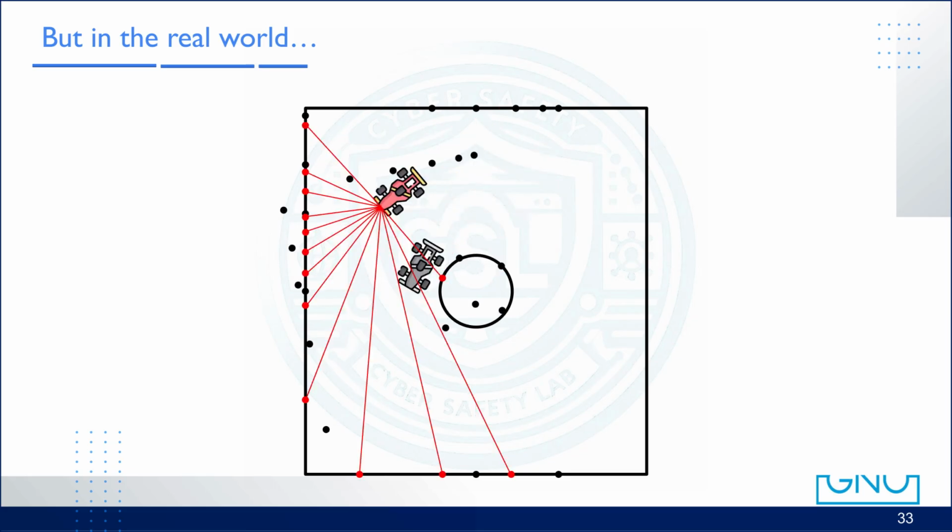In the end, scans accumulated on top of incorrect odometry produce a map that no longer resembles the real environment. Points drift away from walls, straight structures become warped, and obstacles lose consistency. This is exactly why SLAM is challenging in the real world. Even with correct measurements, placing them at the wrong poses destroys the map.